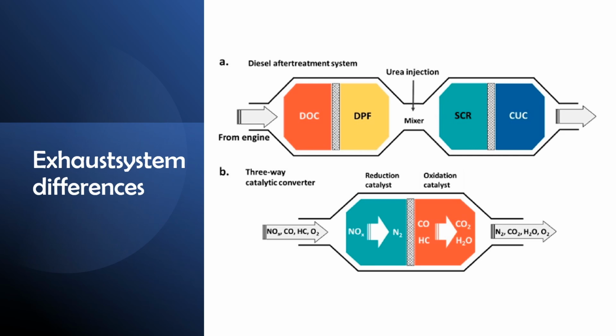That's because a diesel combustion is hotter than a petrol combustion, and therefore there are more nitrogen oxides. And when you have more nitrogen oxides, the reaction in the 3-way catalytic converter would not happen. So you have to split it up, and then you have the same procedure.